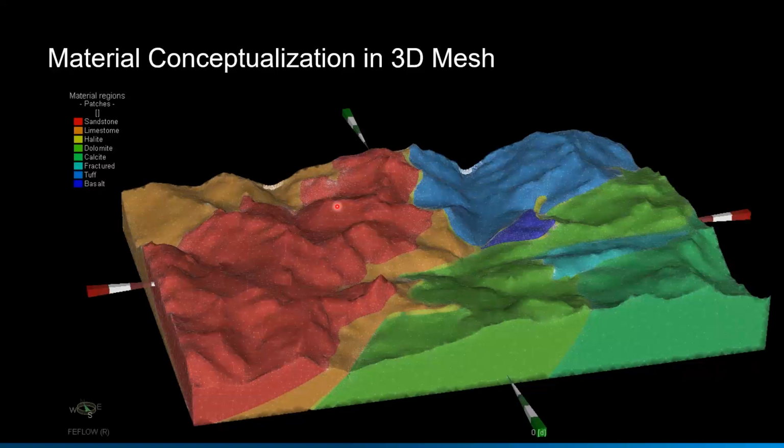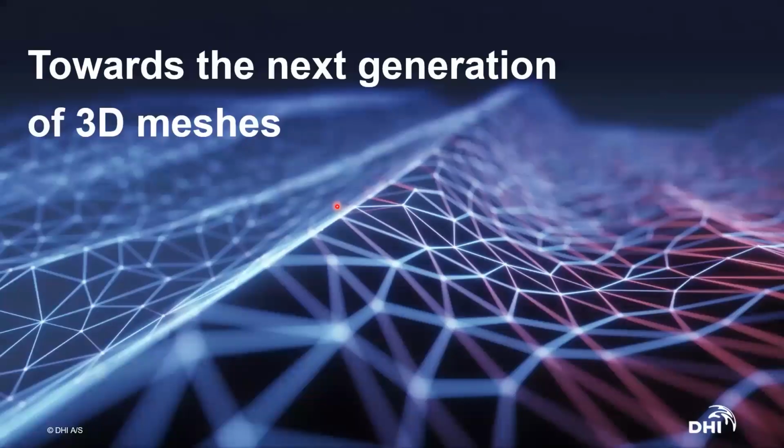Okay, so if you have a proper 3D super mesh, we also have the possibility to implement the definition of materials directly in the super mesh using the concept of the parameter lookup table, with the idea that you put everything in before the mesh is created. When you create a mesh, during the meshing process, FEFLOW will automatically parameterize the entire 3D model domain. Okay, we now know the limitations that happen in these cases of 3D super meshes.